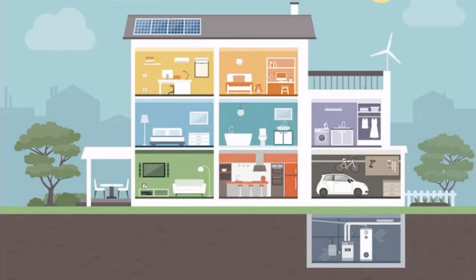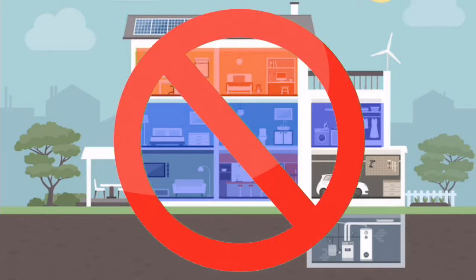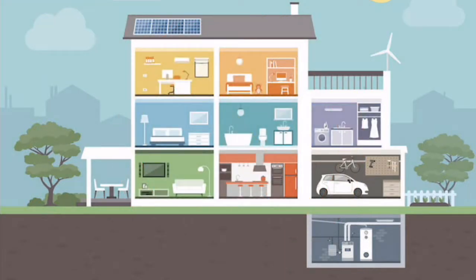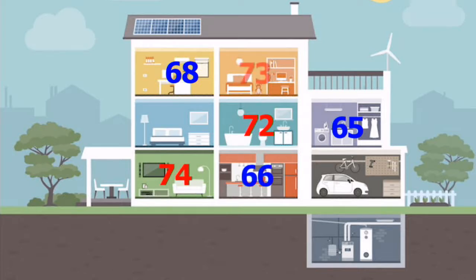But because there is only one furnace and AC, the homeowner cannot simultaneously heat and cool the different zones at the same time. If every room is to have its own thermostat and simultaneous heating and cooling is required, the system becomes very expensive and exponentially more complicated.